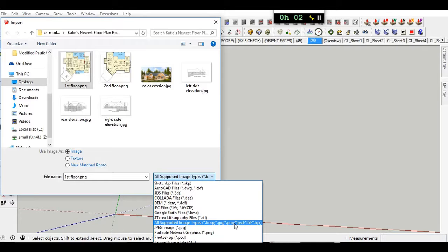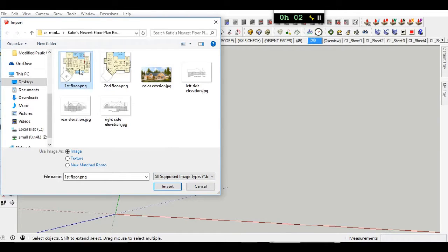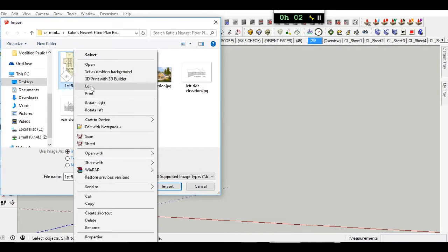T is the standard shortcut for that. You have to uncheck control to get rid of the little plus sign underneath it. The plus sign attached to the little line there is actually a construction line indicator. Line this up with a wall that you know the length of.